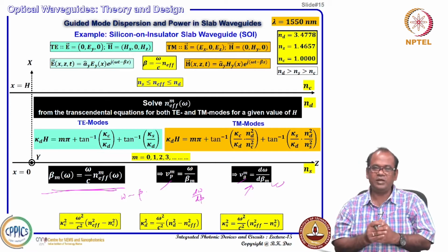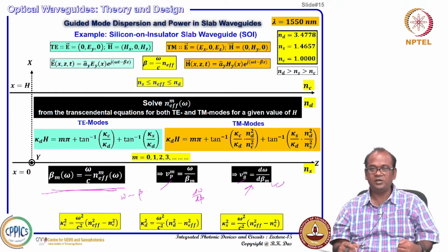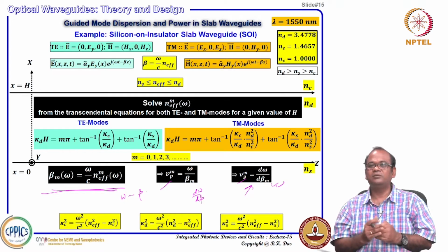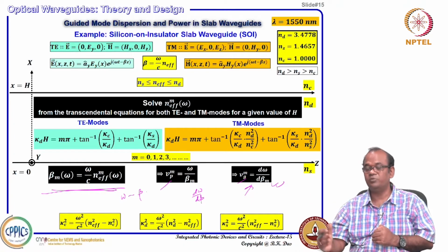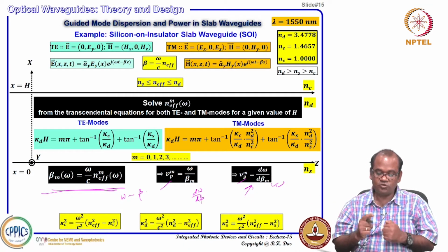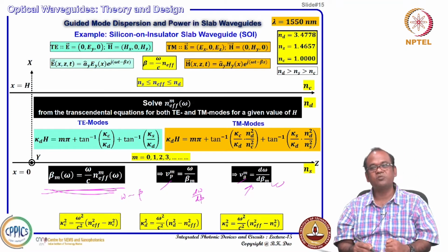information. Though it is very high, close to the speed of light because you are dealing with light, it is the highest speed. But still you can say how slow your information, your data, is moving. So, group velocity is important. That is why it is important to know this dispersion curve, beta versus omega curve.